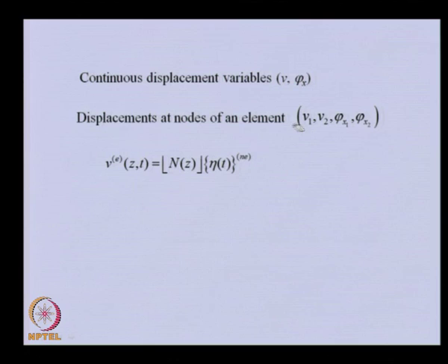And as for the torsional vibration case, the shape functions will be chosen based on the completeness and compatibility conditions of the problem, and that will be done at the stage when we develop the weak formulation of the problem.